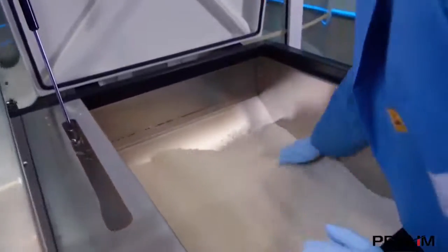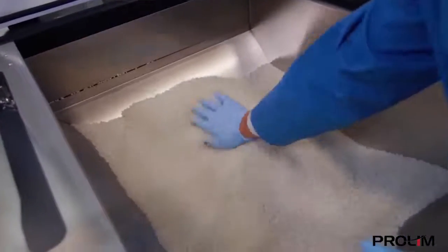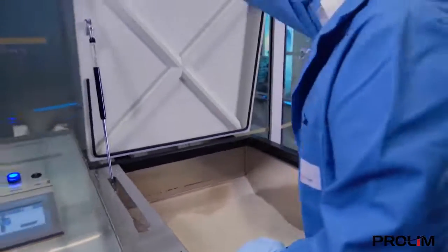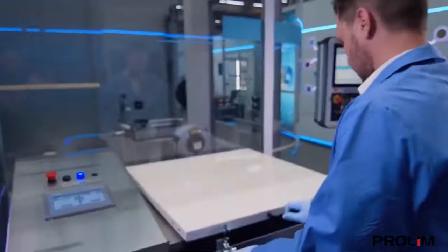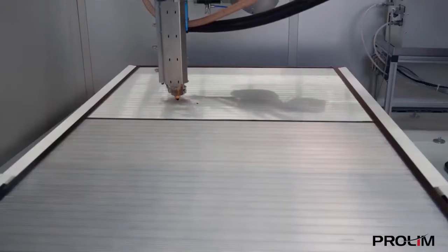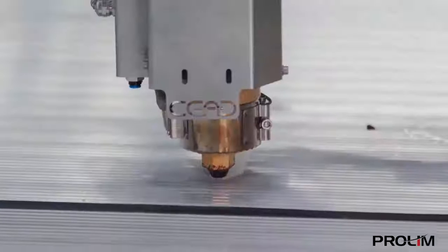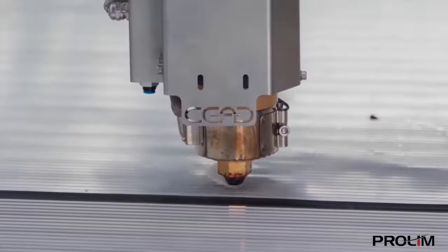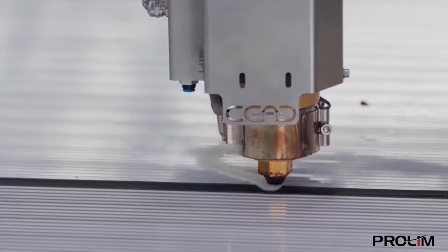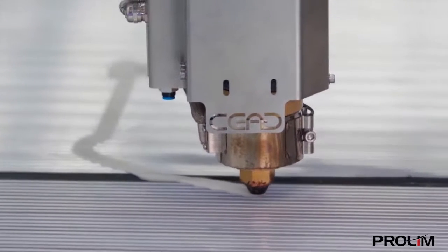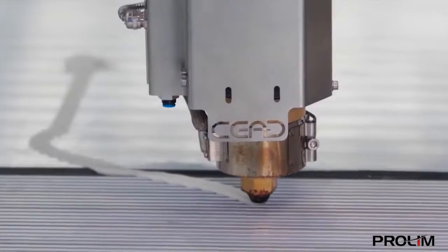So I needed to check the pallets, I needed to refill them, switch on the cabinets, and of course also some warm-up time for the extruder. So then it's very important to start the print process very slowly, because you need a proper bonding between the part and the build plate. It also has a slightly ripped surface, as you can see. And this ensures a proper bonding between the part and the build plate.